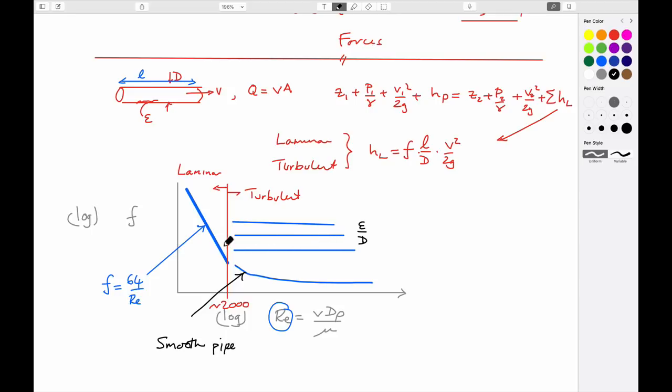And so if you know you're laminar, you can directly calculate the behavior from this. You calculate the head loss, for instance, just by using the appropriate value of the friction factor, where it's a function of velocity, and so you can calculate that directly. If you need to calculate flow velocities where you're in a range where you don't know the flow velocity, then what you have to do is calculate an initial guess. And then what you typically do is calculate